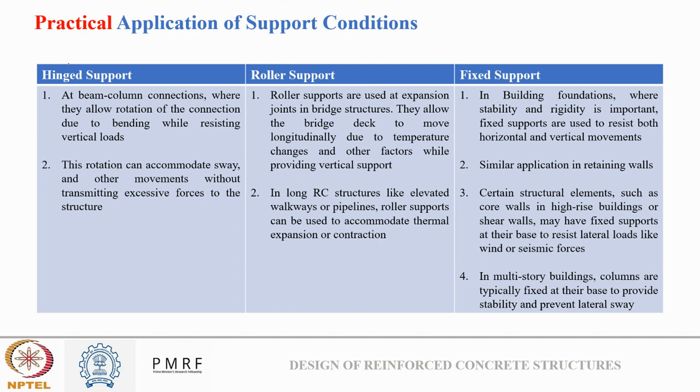Just to have a small discussion on that, we have three kinds of support: fixed, hinged, and roller support. Hinge support means it is able to rotate about the support, but it won't move. Roller means it can move, and fixed means it can't do anything.